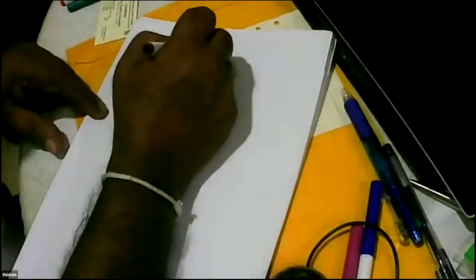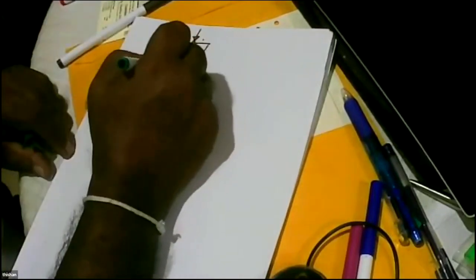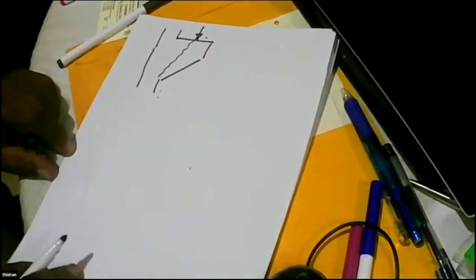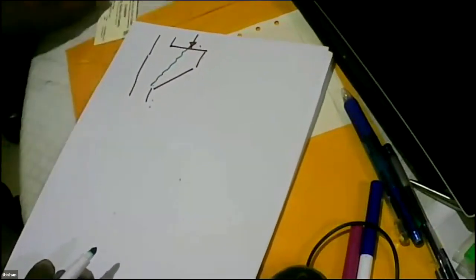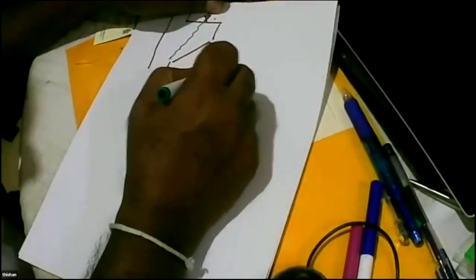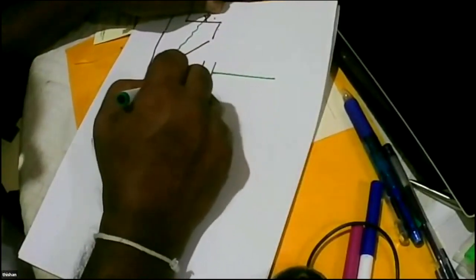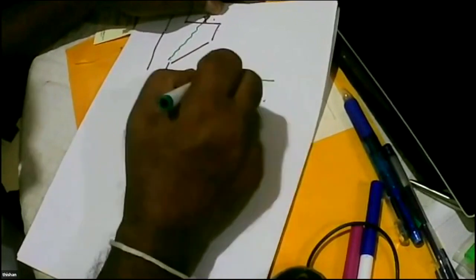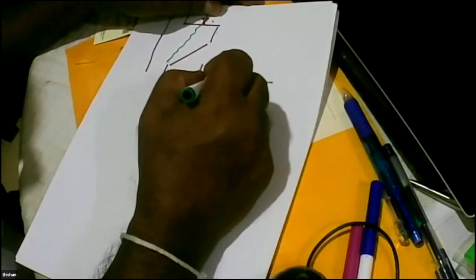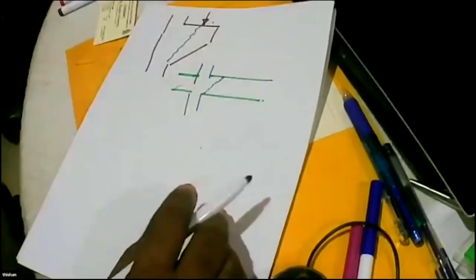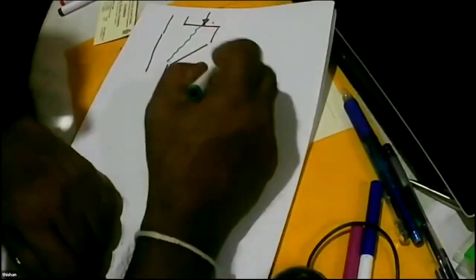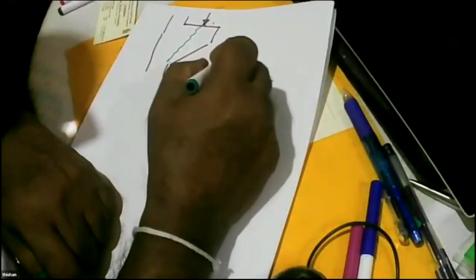We apply a load here. What is the failure plane? Very high angle. So the code says two things. When you are designing for shear, this is a beam. It says, because here to create a failure, the angle is very high, so it has significant enhancement. Because of that reason, it says don't check shear here.